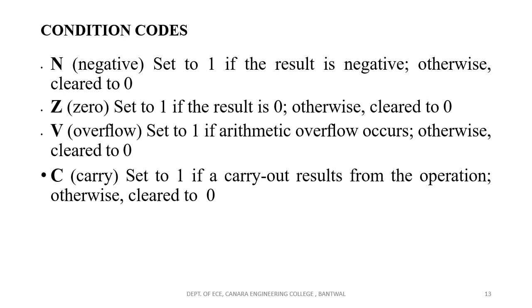Similarly, there may be a state during which the range of the result is more than the range that can be represented by a destination operand. In such cases, the condition is called the overflow flag. For example, if you have an operand which is 8-bit, and the result is 10-bit, it cannot be represented using an 8-bit destination register.